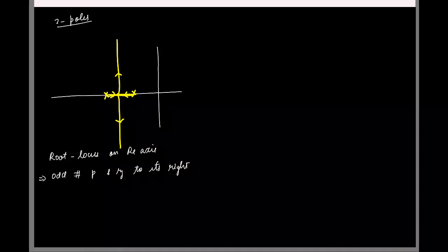So now can you say, can a system with 2 poles become unstable? I have only 2 poles here, right? This is the case. I am increasing the DC gain from 0 to infinity. Is the closed loop pole entering the right half of the S-plane? No. Which means a second order system, in negative feedback, for any DC gain, is going to be stable.